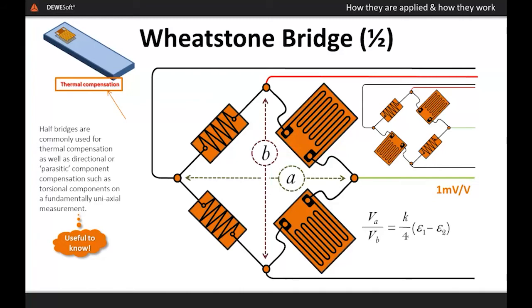Pay attention to the bridge factor when you do your equivalent output calculations, as this is relative to your gauge arrangements. We'll review that later. But one that shouldn't be confused as a half bridge is the dual quarter bridge. This is two gauges in series on the same leg. In this illustrated case, the output is about 1 millivolt per volt. Again, assuming the arrangement is correct, since 0.5 times 2000 is 1000, and the units are microvolts, therefore the output is 1 millivolt per volt.